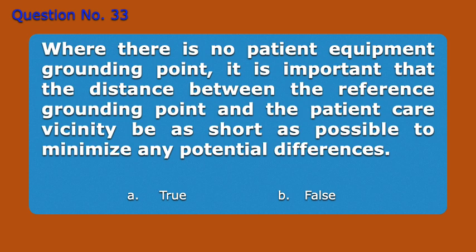Question number 33. Where there is no patient equipment grounding point, it is important that the distance between the reference grounding point and the patient care vicinity be as short as possible, to minimize any potential differences. A. True. B. False. Answer: A. True.